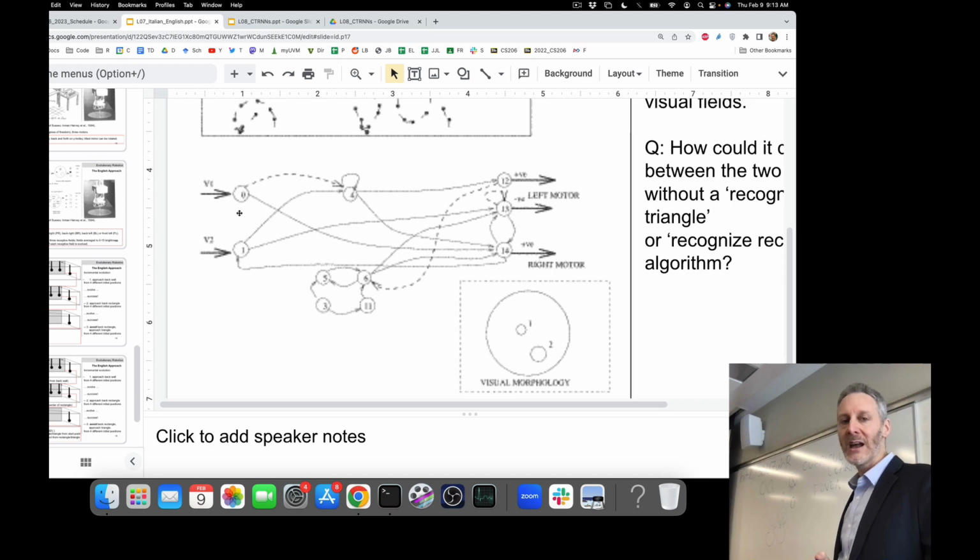All right. So the robot has a total of 7 sensors, but this controller evolved the ability to ignore 5 of them and only use 2 of them. The amount of brightness in fovea 1 and the amount of brightness in fovea 2. So far, so good? So when they drew this, they just didn't draw all of the neurons and synapses that were connected with 0 weights. Yeah, so there's a lot of the material here that evolution has basically pruned away.